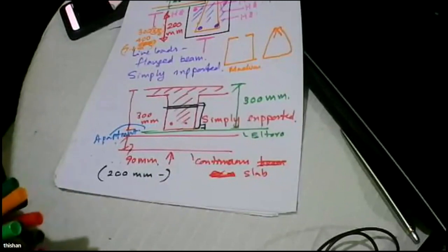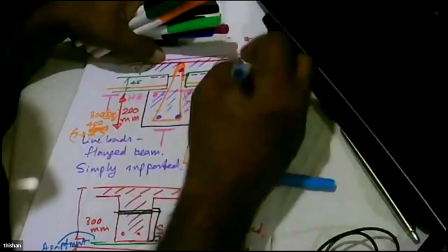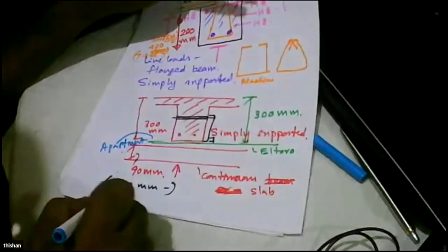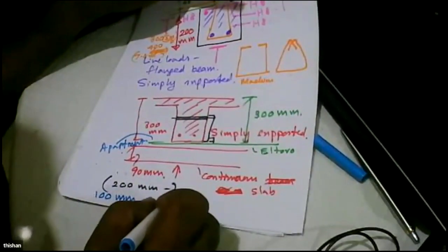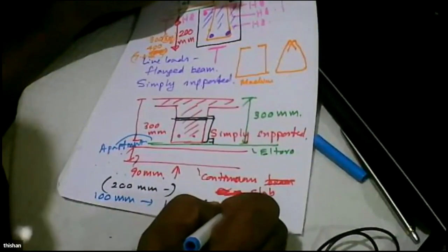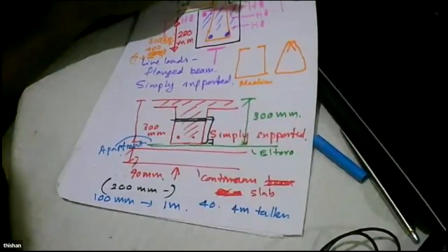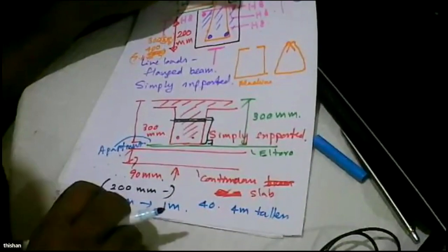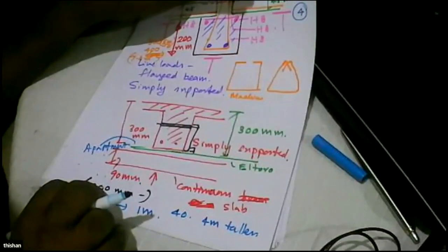So what we do is, now we have a very practical solution, but there is a cost penalty of 400 millimeters per floor. So 10 floors, your building will be 4 meters taller. 40 stories, the building will be 16 meters taller. Not a major problem because it's only about 5 floors taller, but we can make a significant saving in steel.